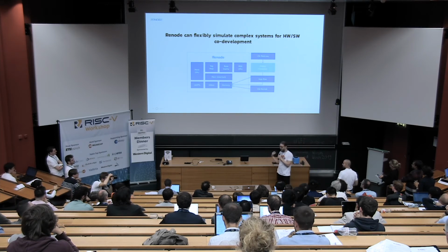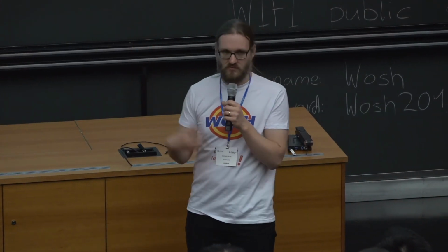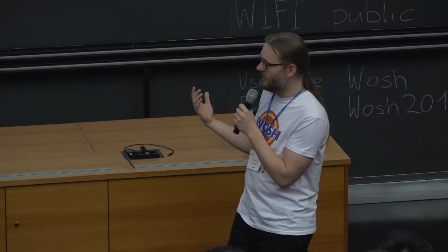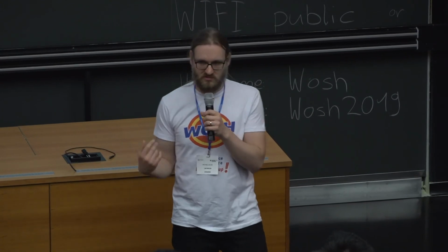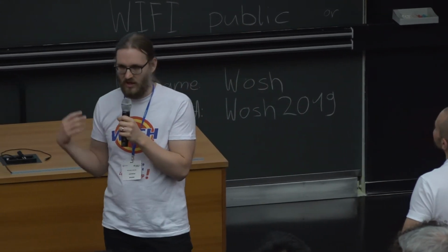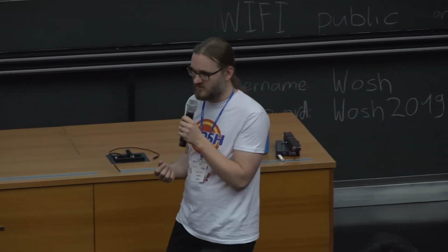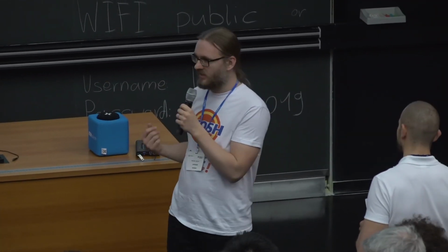What the poster contains is a whole hardware-software co-design flow, which involves modeling things in Renode for fast work, and then also simulating those things on an FPGA, where the work with Renode is multiple times faster. So it allowed Dover to go from several weeks to develop a new feature to several hours or perhaps a day to build something new. We allow to do this through a flexible language and scripting framework, but also we have additional functionalities such as co-simulation with Verilator, as well as we can actually co-simulate things between your PC and an FPGA.